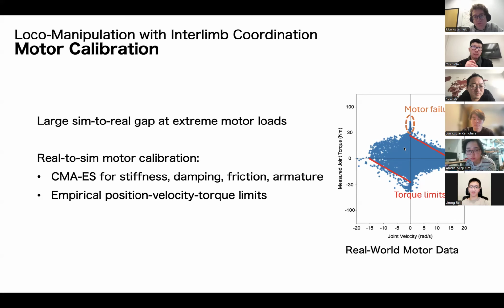So the Beyond Mimic is really robust. So I think now, if you wanna deploy some RL policy on the G1, you can directly adopt their PD gains from Beyond Mimic. Yeah, I tried that. It's very robust. Cool. All right. I think Feiyang is doing that.